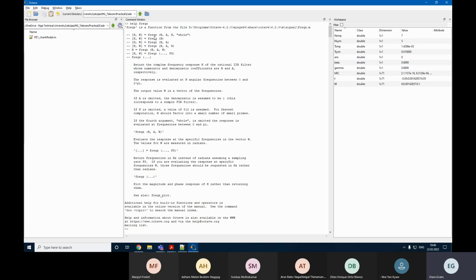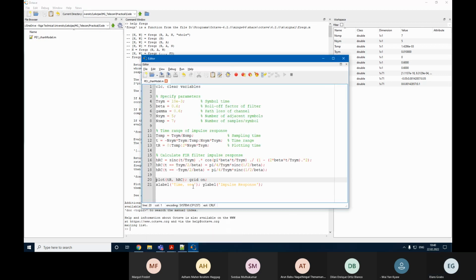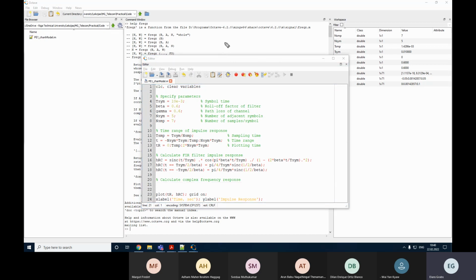Yes. And the result, it produces the complex frequency response H capital. So let us do that here by calculating a complex frequency response. This way, you also get familiar with how you can actually check a filter's frequency response. What you need to do is, in general, our frequency transfer function in Z form for any type of digital filter is specified like this: